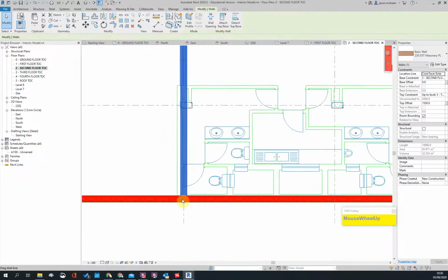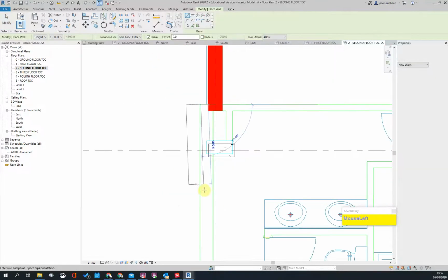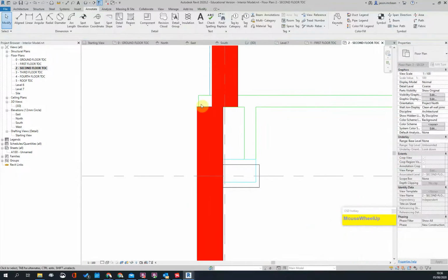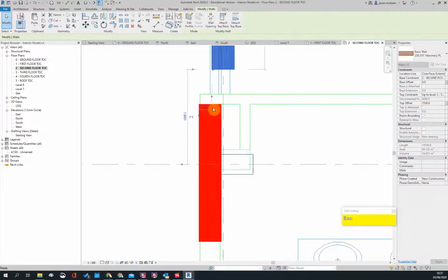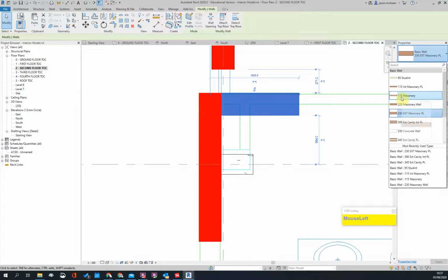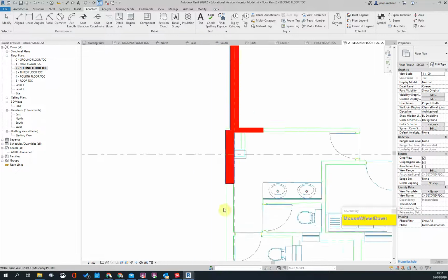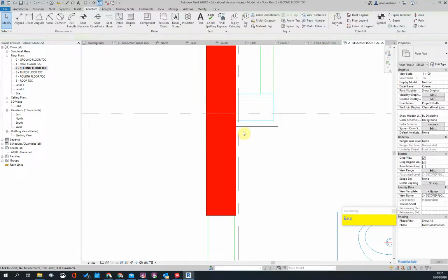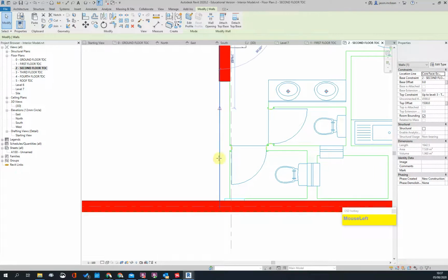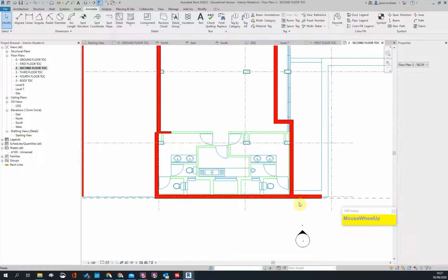So let's stop this guy here, pull this back, create similar. Third floor. I've got the elevation to kind of sort this out. That's fine. This wall I'm going to pull back, create similar. Core exterior. This is going to be a 110 wall. And then TS up to there. Okay, this, yeah, I see this is slightly concerning, this line here, but that's fine. We can fine tune that. This will trim from there to there. All right, this we can trim.